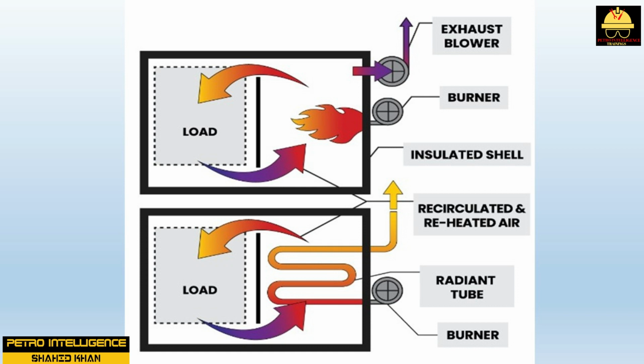This type of heater is composed of a shell and a series of steel tubes designed to transfer heat through the combustion chamber, tube, and into the horizontal fire tubes. Exhaust fumes exit through a chamber similar to an exchanger head and pass safely out of the boiler. The water level in the boiler shell is maintained above the tubes to protect them from overheating. The term fire tube comes from the way the boiler is constructed. A fire tube heater consists of the boiler shell, fire tubes, combustion tube, burner, feed water inlet, steam outlet, combustion gas exhaust port, and tube sheet.